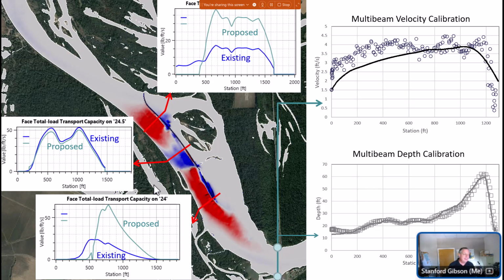And so here's one, and incidentally, ERDC went out and got ADCP data, which is just beautiful if you're doing 2D modeling, especially if you're relying on the hydraulics and your sediment transport isn't going to kind of tell on you. And so we calibrated in several places to the depth cross-section and the velocity cross-section. And then we're analyzing this structure right here. The structure is not out there now. That's part of the proposal.